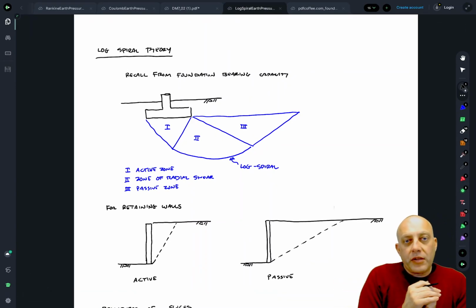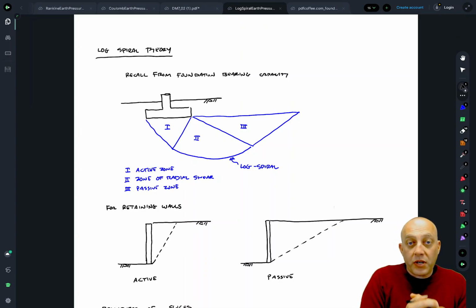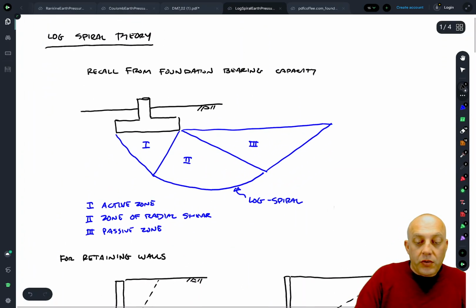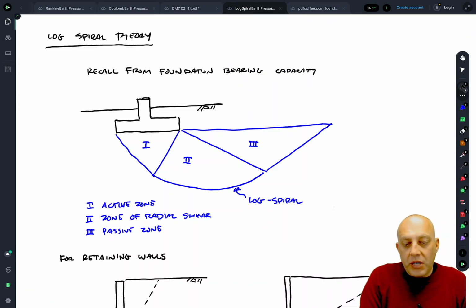In this video, I'll talk about the log spiral theory, which is very commonly used for passive earth pressure problems, just because the assumption of a planar failure surface is wrong. And so what we'll do is first talk a little bit about the log spiral.